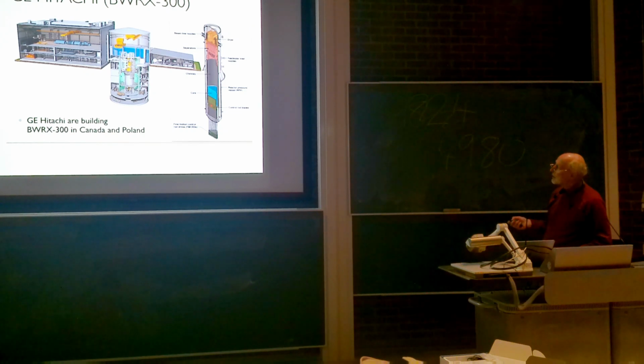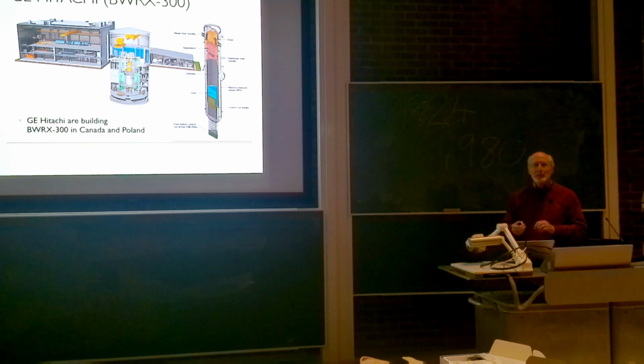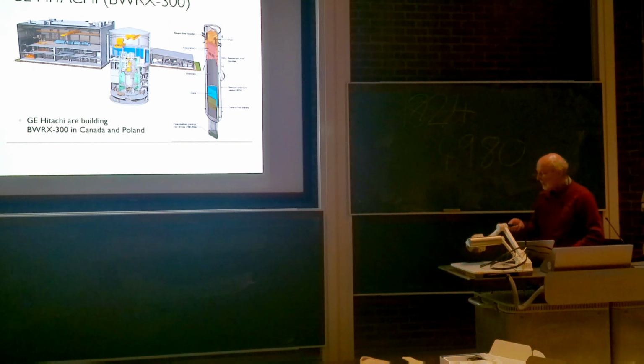And if you look at the cutaway of the pressure vessel, then here's the reactor core, here's the separator to separate out the steam and then to dry the steam before pushing it out. But because you have all this gubbins up at the top, it means that your control rods have to come in from the bottom. Again, normal practice is to let gravity or assisted gravity push them down rather than have something that's got to push them up. But if you've got all that stuff at the top, you can't do that. So here, normal reactor system with turbines nearby to produce electricity.